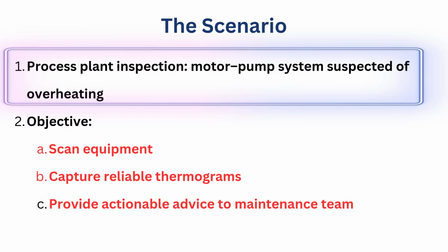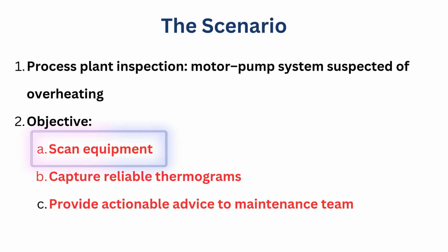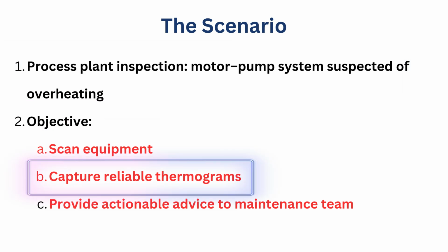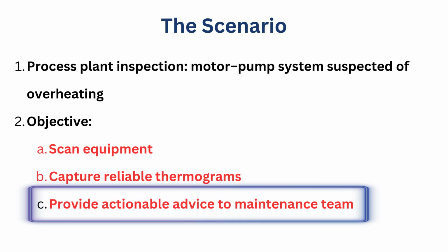So what will be our goal? Our goal is to scan the entire equipment and capture reliable IR images, and advise the maintenance team using all our experience and expertise in thermography, and try to find the actual root cause of why this overheating problem is there in the system.